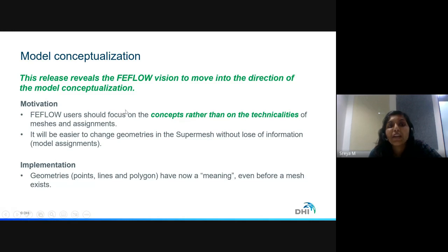There you plan what all is there. Why we do this planning is because in your model you may need some regions with a finer mesh and some with a coarser mesh. This is one topic we usually use when we talk about modeling. Finer mesh means a larger number of elements, more triangles. More triangles means more equations are solved there, so your result accuracy will be higher. But it's not necessary to give more elements in all locations.